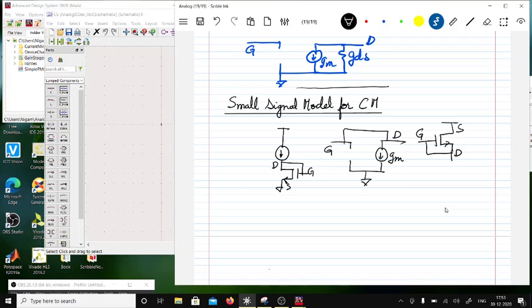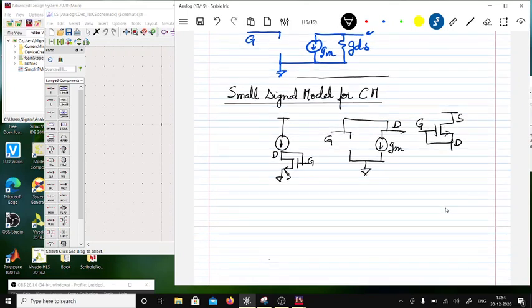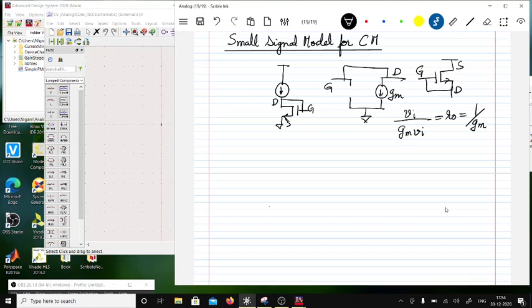It's just a question of polarity between NMOS and PMOS, so it really doesn't matter. So when I do this, I know that the voltage across drain source is going to be VI, and the current through it will be GM VI. So the output resistance is equal to 1 over GM, right? Now in this case, I have ignored GDS. So if I include it, it would be 1 over GM in parallel with RDS.